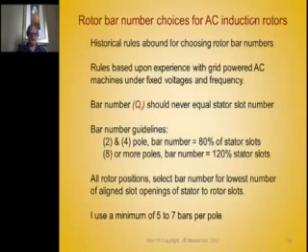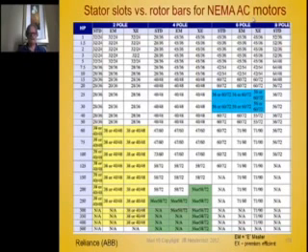So you want a sufficient number of current carrying conductors in parallel between them to properly define a pole and make sure it looks sinusoidal. That's the only way I know to explain it, to give you a feel for why a reasonable number of bars is required.